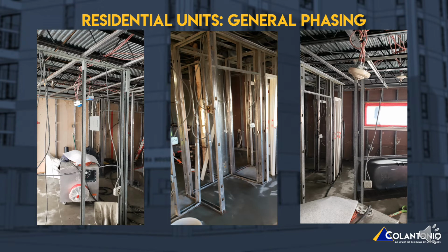As part of alternate number 2, the drywall in the kitchen and bathroom will be fully removed, but the remainder of drywall in the unit will be cut and patched in lieu of full removal. In this instance, MEP trade contractors will be required to mark out locations of cutting so that the abatement sub can provide the necessary in-wall access.